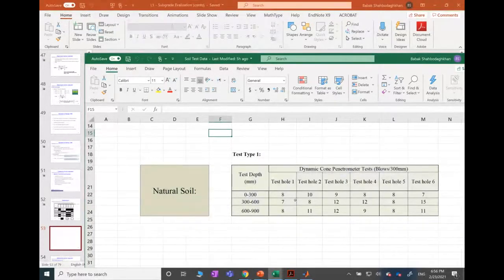In the lecture notes of 9525, 50% passing is considered as fine grained soil, but the rule here is 75%. So which rule? Yes, the definitions can be different. For example, in soil classification, the unified soil classification system has some rules.